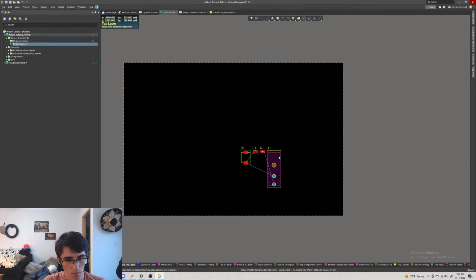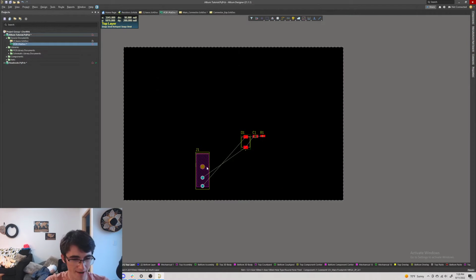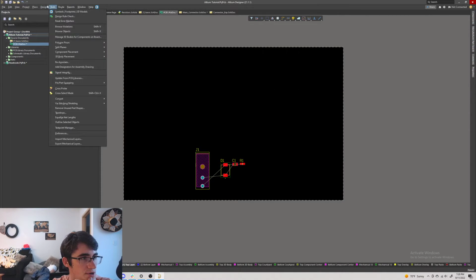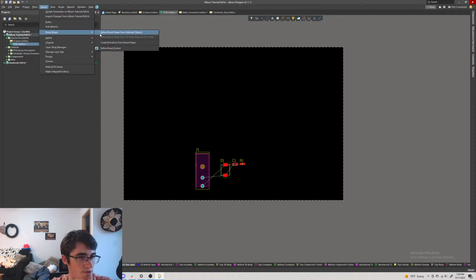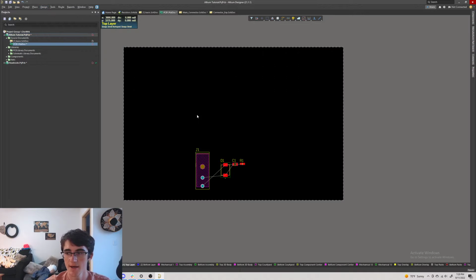So one general practice that you'll see is you want to put connectors to your board on the edges of the board. And you're going to say, hey, this pseudo circuit is tiny. This default space in Altium is huge. So you actually can change the size of Altium's PCB. And you can do that under design and then board shape. And then you can do it by selecting define board cutout. But like I forgot to do, you need to define it with a certain shape first.